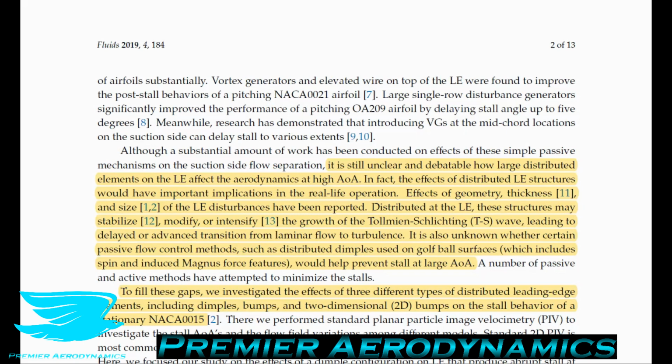Very small disturbances are disturbances where the boundary layer has a disturbance and it's so small that it gets damped out and you won't transition to turbulence. Very large disturbances is where you have something called bypass transition. You have this massive disturbance which just jolts the entire boundary layer into being turbulent. It just creates all this turbulence out of nowhere and you're now turbulent. TS waves are sort of in the middle,